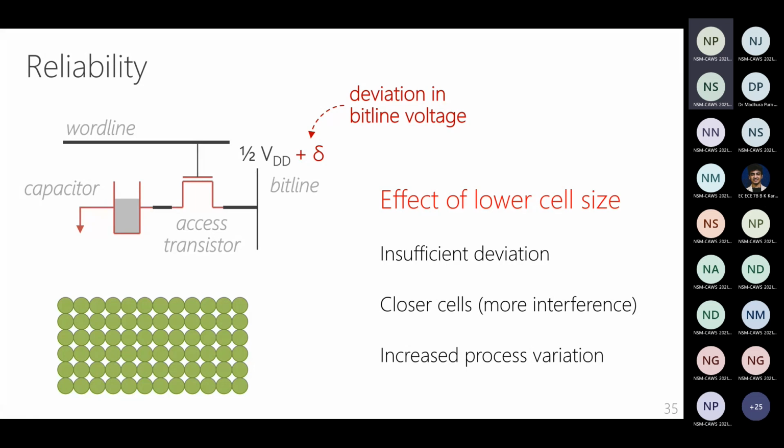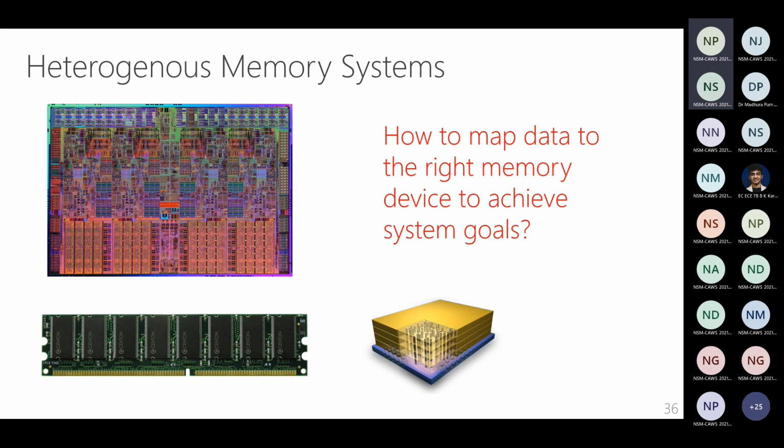I think this is one of the biggest scaling challenges in DRAM, to be able to scale it to smaller and smaller sizes, because as this capacitor gets smaller, we're actually talking now about tens of electrons being stored in a capacitor as charge, as opposed to anything more non-trivial, right?